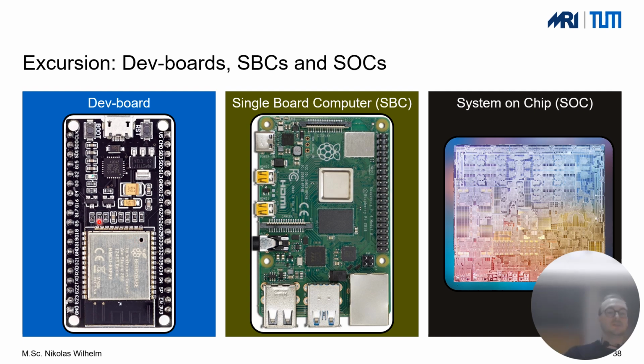One thing you might classically know is something like Arduino. This is actually from the class of development boards. So this is a single microcontroller on that respective development board, and it has additional external circuitry, something like a boot reset and some decoupling capacitors. That means if there are some voltages appearing for the microcontroller, this ensures that the microcontroller will not be destroyed, via these decoupling capacitors. So that's a very simple and basic board, and the main thing is you have a lot of input and output pins that you can access this microcontroller with to later connect some sensors.